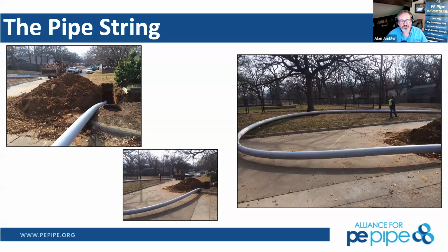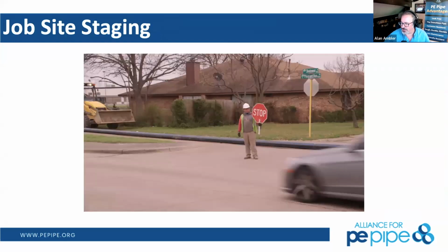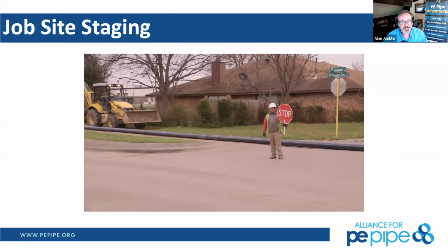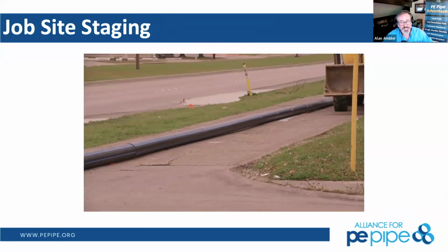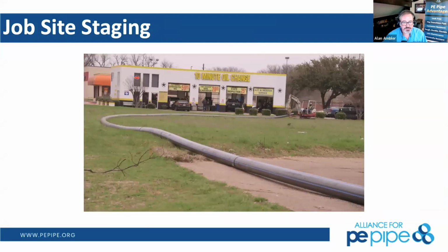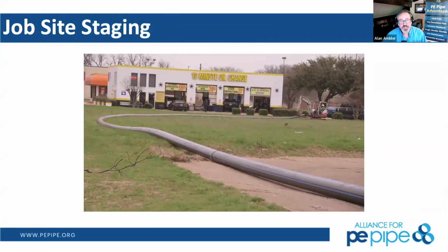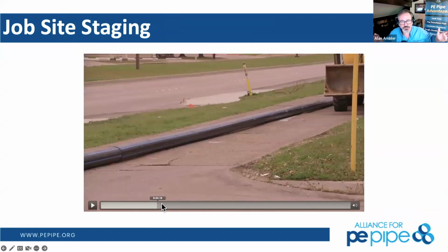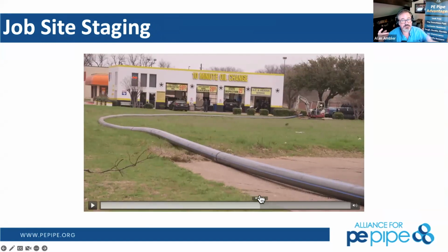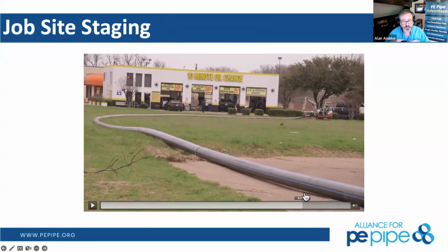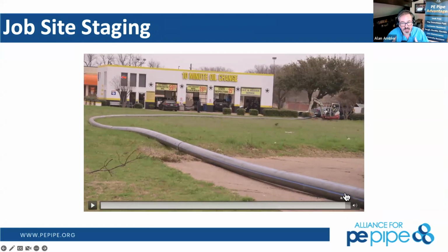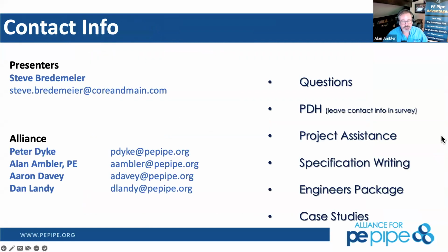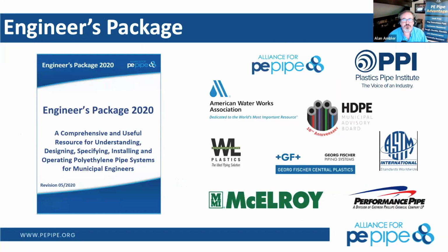Allowable bending radius, how forgiving it really is in order to be able to push this pipe through and install in that manner. So in tight neighborhoods, that's just a godsend to be able to make sure that we can get the pipe in. Most laydown yards that we're going to be looking for are going to be long and longitudinal, where we can have even as little as one employee fusing up all of your pipe beforehand, and the other employees can be out there doing restoration or third-party utility identification or other things of that nature. Then you'll pull that pipe into place.